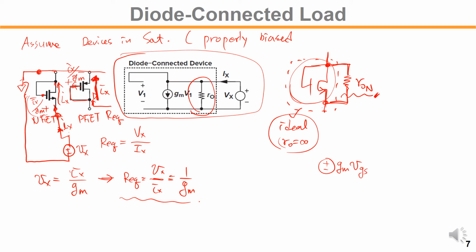So this model, gm VGS, right? So this is the gate. So gate is tied to drain. I'm sorry, this is the current model. So this is a VGS like this, right? Every time you see the transistor, it is very inconvenient to draw the small signal equivalent model. We will directly analyze using this transistor symbol.